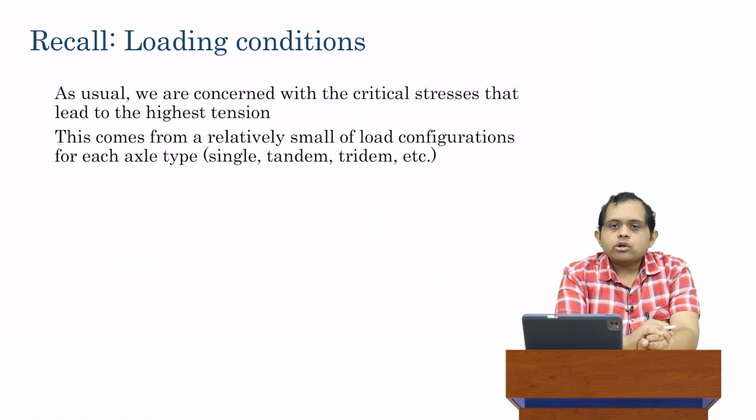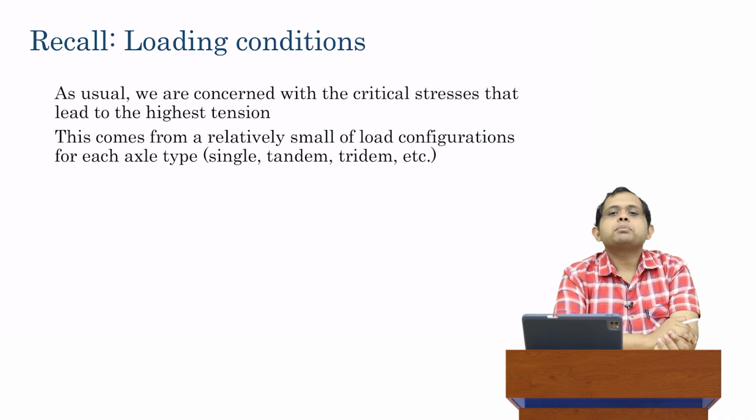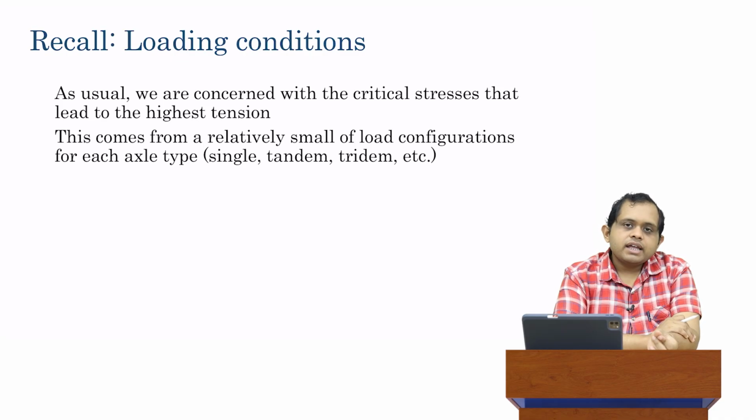Okay. I also wanted to talk a little bit about loading conditions. Remember, when we apply a load on the slab, we are going to get stresses. Stresses are going to be obtained at every point. In particular, if you are doing the stress calculation using the finite element method, at every node we are going to get some amount of stresses.